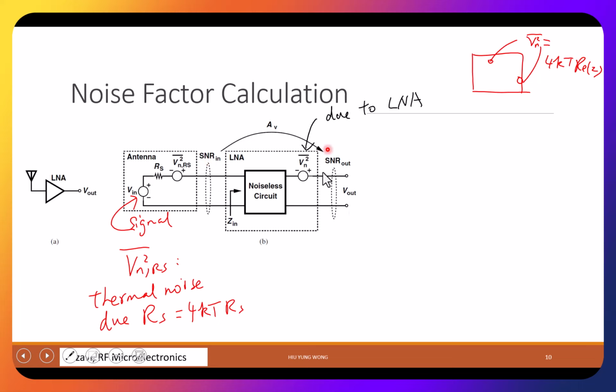When you reach this point, you have another signal to noise ratio. The amplifier has this gain. Now, do not forget, the amplifier also has an input impedance, the LNA. This is going to affect our noise figure also, as you will see later. Okay? Any question about what we are setting up now?